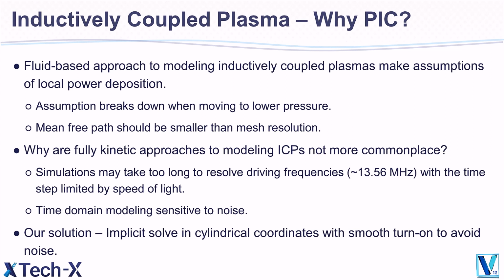So this means that the assumption will break down when moving to lower pressure because power really is only removed from the field due to collisions between particles. The mean free path needs to be resolved on the mesh, and the time step needs to be low enough to allow for resolving the collision frequency.